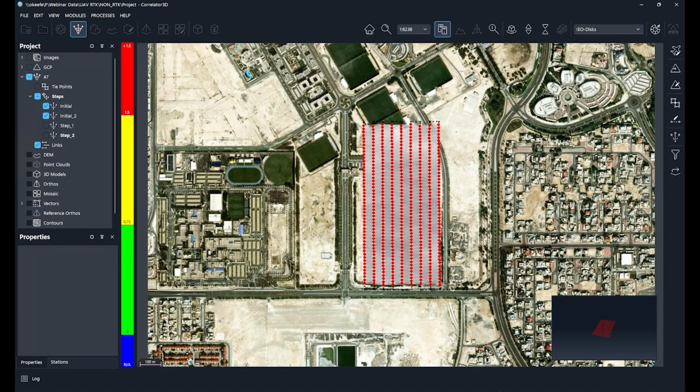If you already did exhaustive extraction and you see a couple of images with no tie points, the next question is: is it RTK PPK corrected? A lot of folks working in dense forestry opt for RTK or PPK corrections because they don't have the ability to add a GCP in the field, as we were talking about during our webinar.